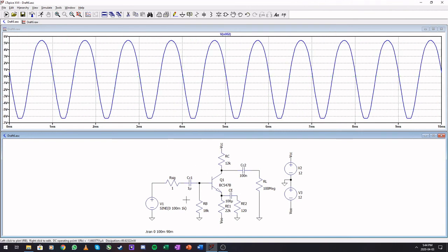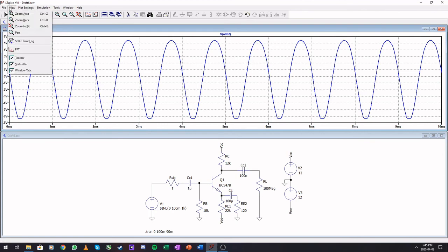Okay, so this is a very good example of this transistor not being in the linear region anymore, or not being used as a linear amplifier anymore. And people tend to forget that this input signal here is very much related to that. In the previous one, we could up this signal because we had a larger resistor down here. Okay, so let's quickly check the effect in the FFT for this one.